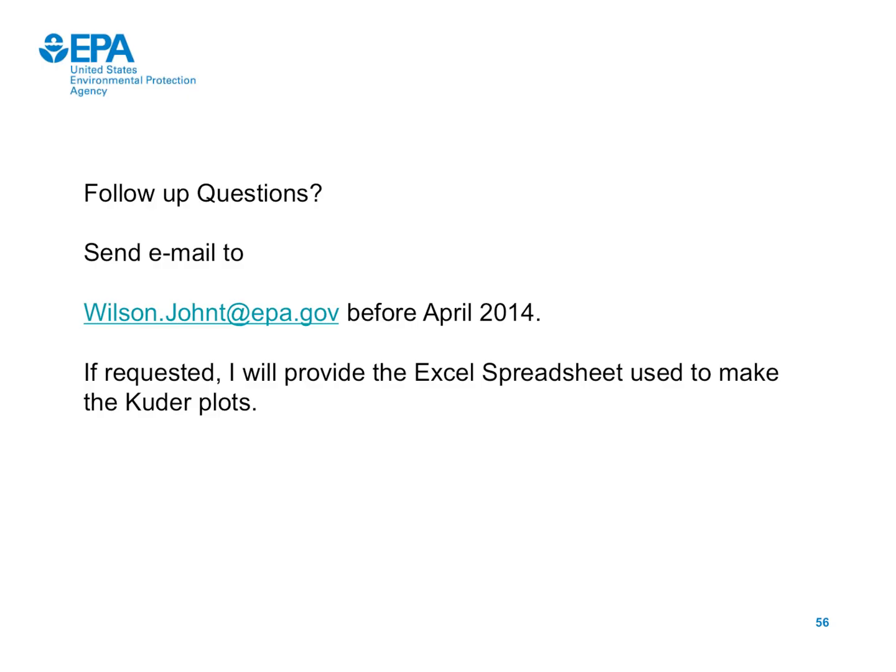Okay, can you also briefly reiterate how you and Pat came up with the boundary conditions on the DEL for the daughter products? Was it based on the site data? Okay, it's based on the idea that iron monosulfide, FeS, also abiotically degrades TCE to primarily make acetylene, which you don't pick up as a daughter product. cis is a minor degradation product in that pathway.